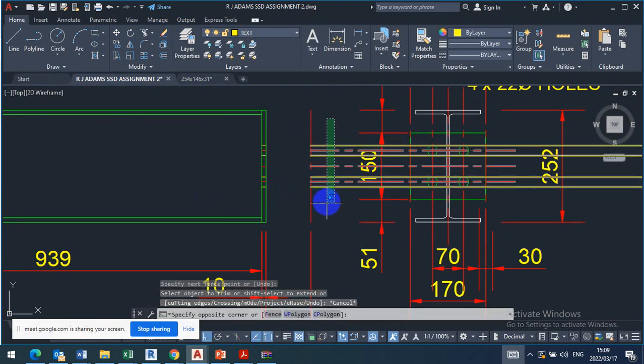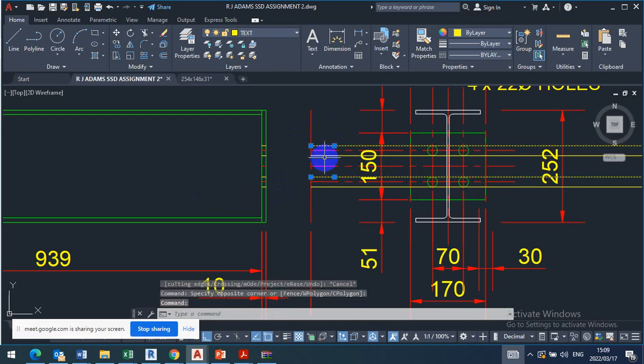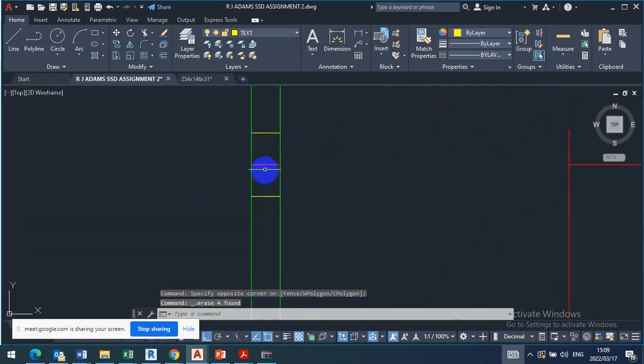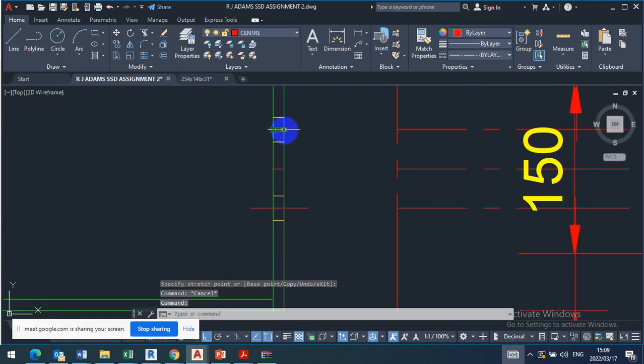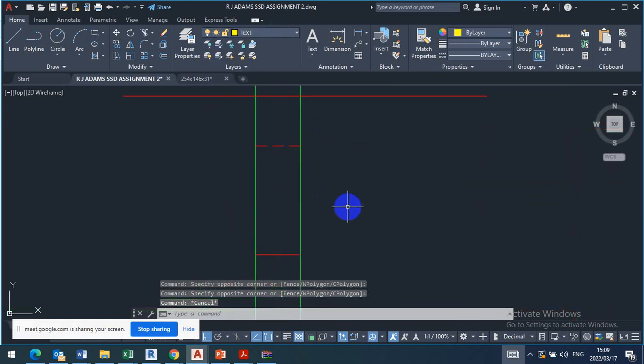Trim. Then you can delete the yellow ones. And remember, it's a mirror image of what we need on the left hand side. This center line needs to come out a bit. The yellow lines must be in hidden lines because those are both holes. They're inside the material. So you have to change this yellow to hidden line. Come here, you say hidden line. You see?